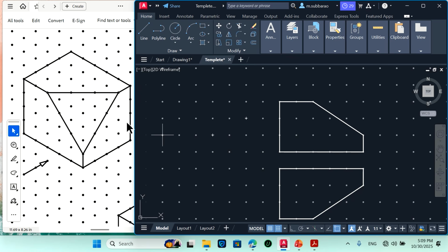So you will take a line, and draw this line, and again 40 mm and 10 mm up, and here also 10 mm. So I completed this surface, and these 2 points I will join along with this, and this is 40 mm, and this is also 40 mm, and 40 by 40, and then I will be joining these two, in the side view.